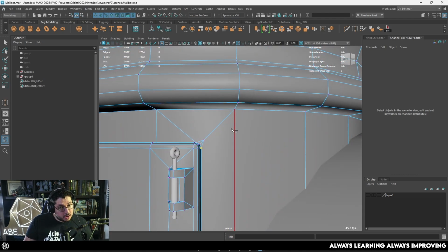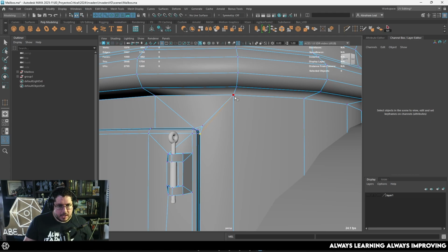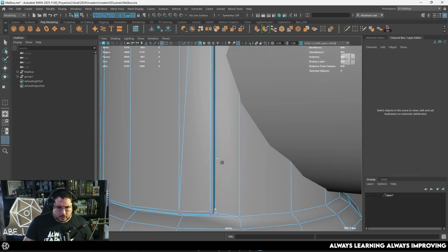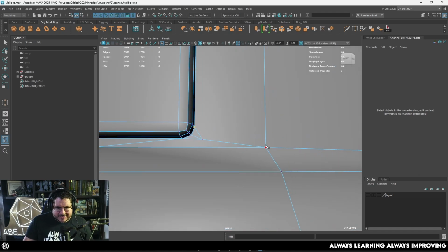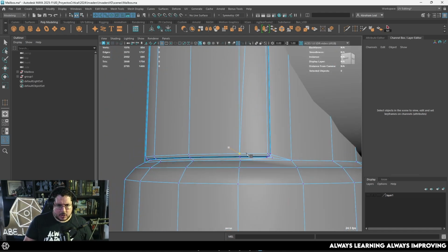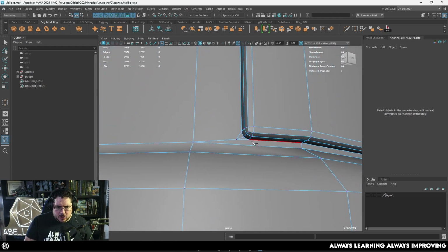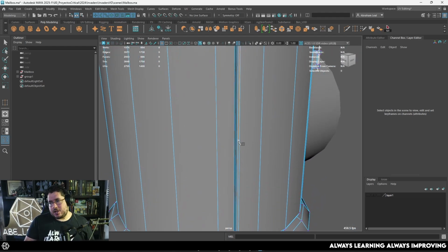If you're doing characters, that's a whole different story, okay? I have a whole series about that, like how to retopologize characters for proper animation and stuff like that. But for hard surface stuff, doing this, it's called stitching. It's perfectly fine. What you want to avoid is having any n-gons, because as we know, n-gons can mess up topology. And I know we're gonna get a huge debate.